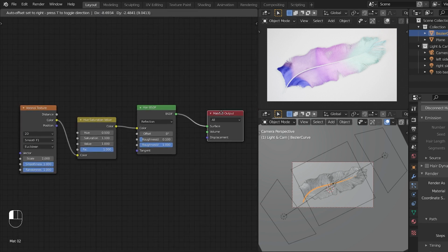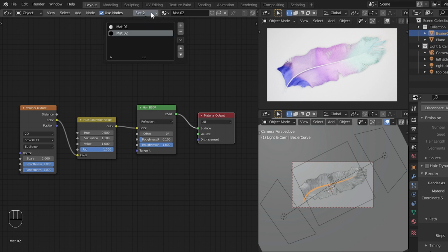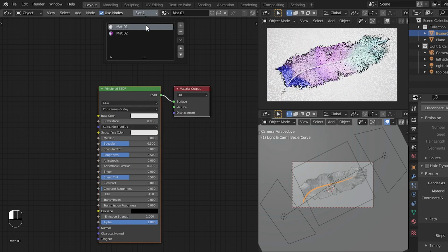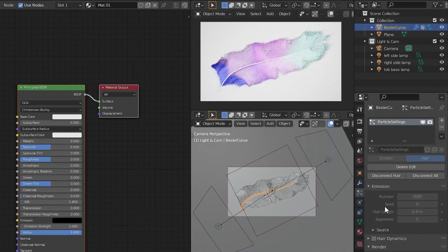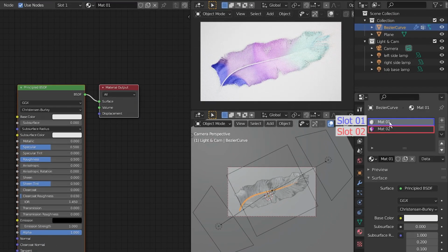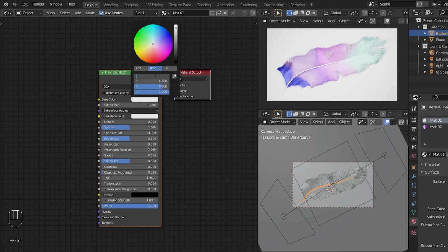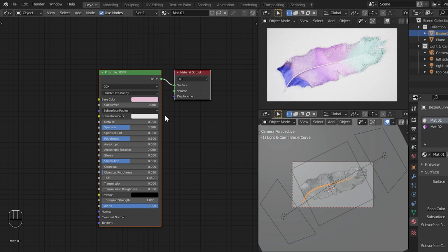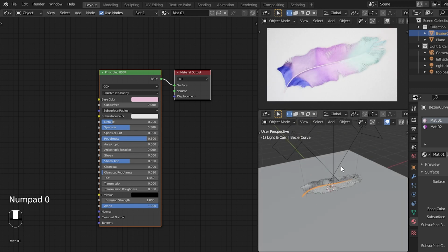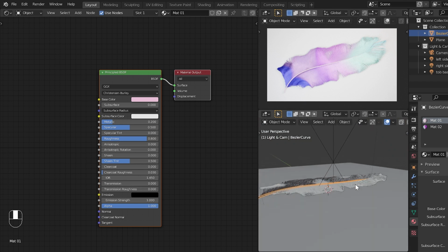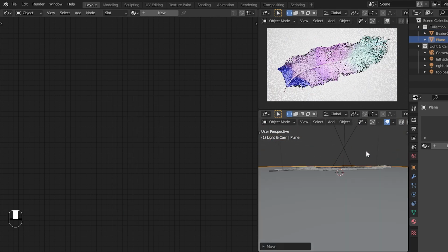Now let's make the material of the Rachis. So, first, select material slot 1 here. Now enter the HSV values given here for the base color of the principled shader. Then give it 0.2 for metallic value and 0.8 for roughness value. Okay, we have now finished creating the materials for this feather. Before the rendering, here set this ground plane so that it is close to the feather.